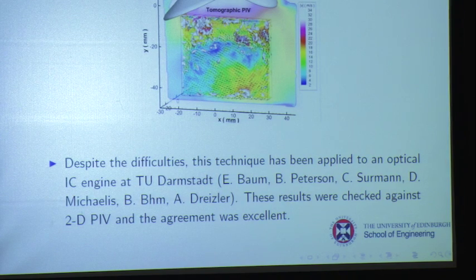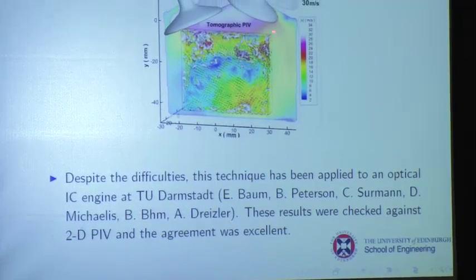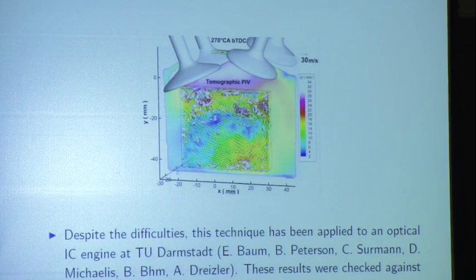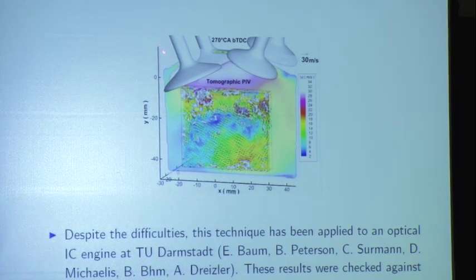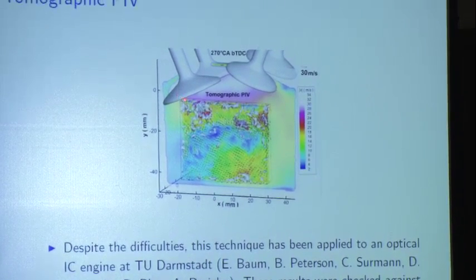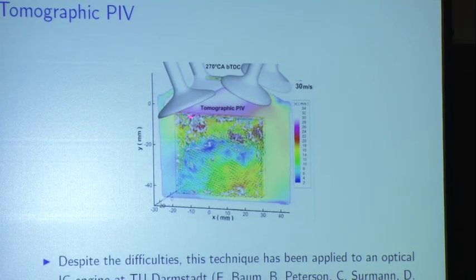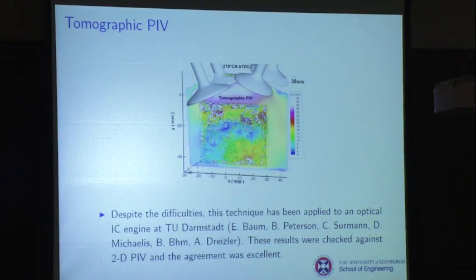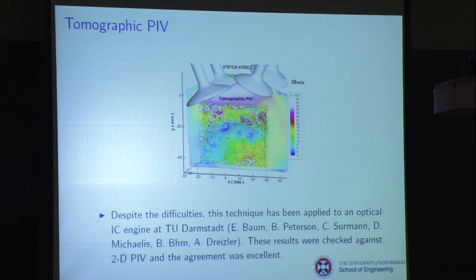So here's a picture from Brian's work where there's a volume in depth there. This is inside a piston engine. It's motored, so it's not fired, okay? And notice that the injector was up here, and he cuts off the tomographic PIV to this point because above that point, all those spray issues we discussed are happening, and so they just eliminated that data. And so what you're looking at here are velocity vectors, and these are isosurfaces of vorticity.